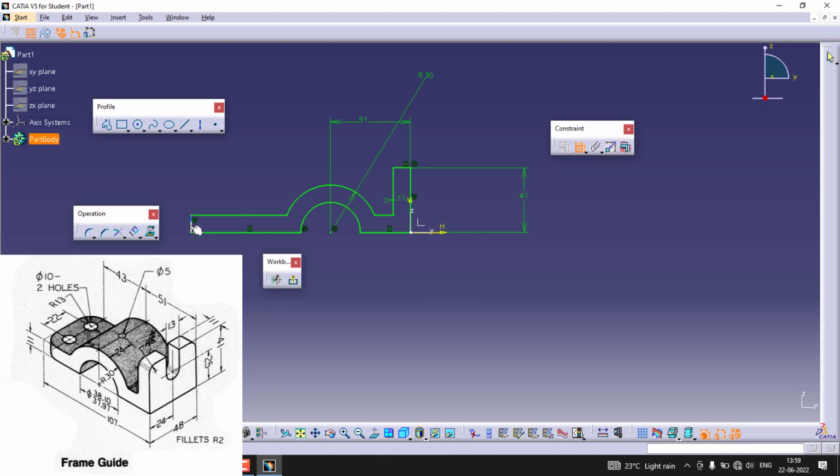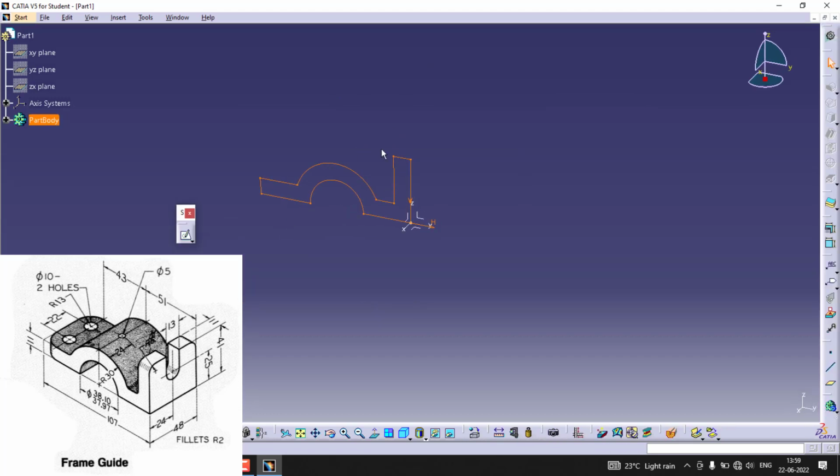ISO constraint and a constraint, it is in CATIA. Okay, so you can define the distance, that is 107. So we forgot to add it. I'll add it, 107 like this. Okay, so done with this, you can simply exit the sketcher workbench, and you can use the tools.